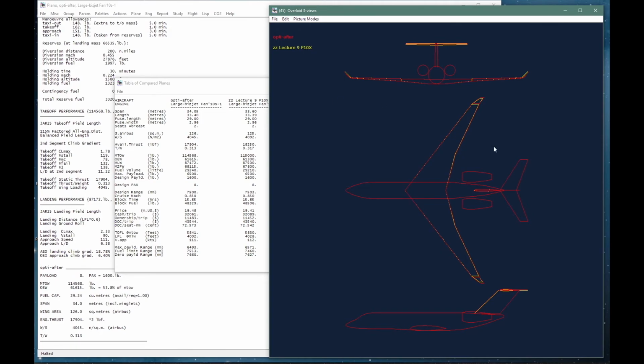Let me say a few final words about fuel capacity. Once again, for this class of aircraft, geometric fuel capacity is critical. We noted good accuracies in our predictions of available capacity for the 787 and A350. But in general, there will be considerable statistical uncertainties until a complete 3D structural model can be produced. Wing interiors have very intricate shapes, particularly near the root, where fuselage or saddle tank contours will vary a lot. What we can say, however, is that there is every indication that this wing is big enough and no fuel capacity problems are expected.